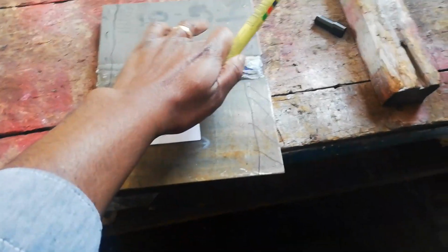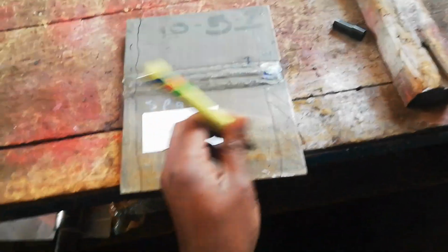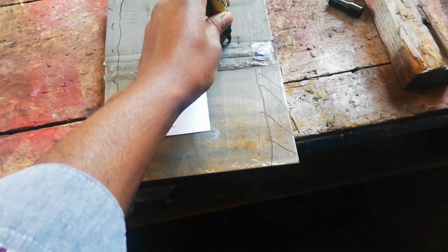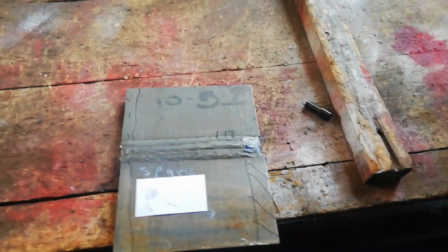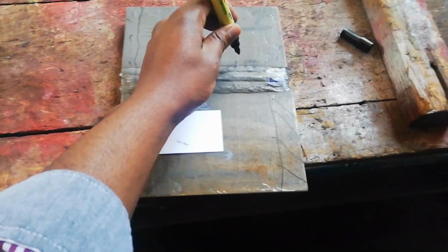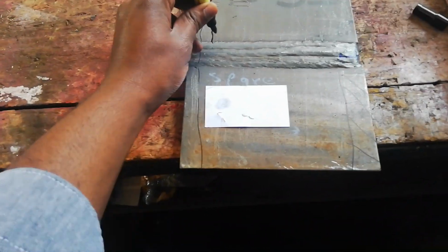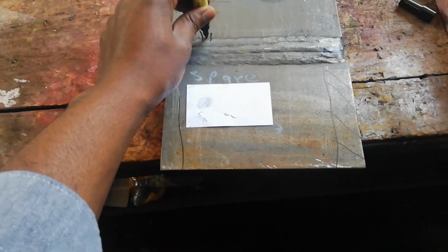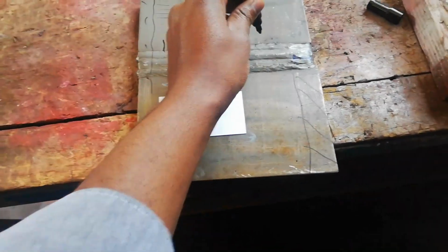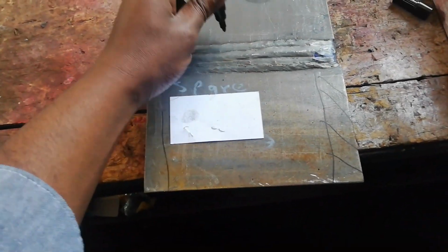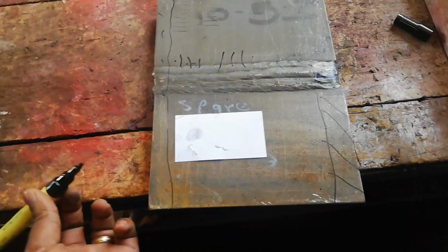So once that is done, we're gonna cut our first tensile there. After cutting our first tensile, we're gonna cut 2 bends. Let's say that we are dealing with an ISO, so 2 bends there. So 1 tensile, 2 bends, and here again we come for our second tensile and 2 bends. We're gonna have 4 bends, 2 tensiles. After doing that, we're gonna go for the impact in the middle here. We're gonna get our impact and our macro somewhere there, right?